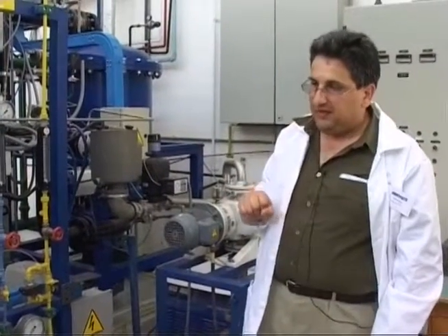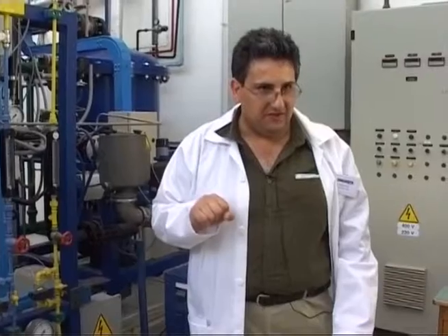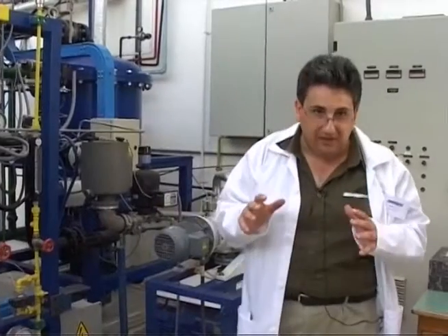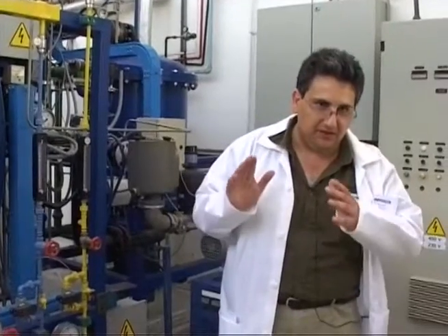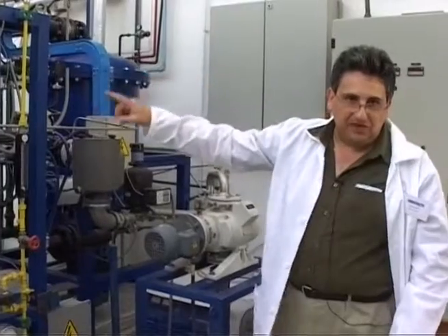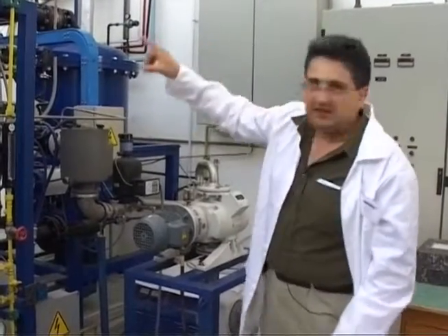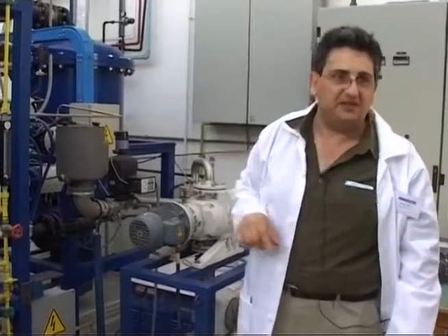The next step is to cool down the components. Once the components have achieved the required depth and the required amount of white layer on the surface, these must be cooled rapidly to stop the diffusion process. If the nitrogen supply is interrupted and the components are allowed to cool slowly, nitrogen from the surface will keep on diffusing and thereby the surface hardness will decrease. So a large amount of nitrogen is introduced rapidly inside the furnace and circulated through a heat exchanger. This will cool the furnace rapidly and stop the diffusion process.